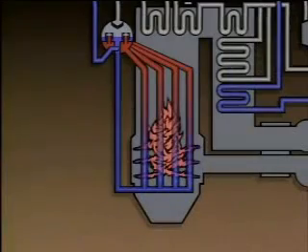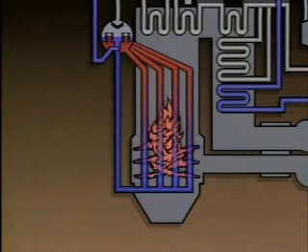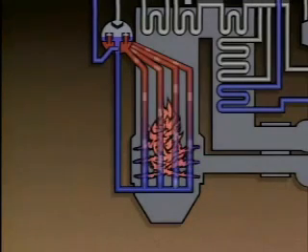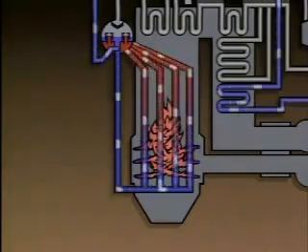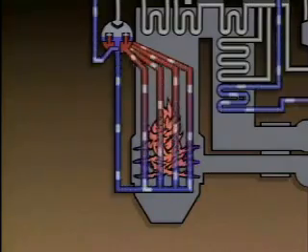The flow of water through some boilers occurs by means of natural circulation. The key to understanding natural circulation is the fact that cold water is heavier or denser than hot water or steam. In a boiler, the mixture of water and steam in the water walls is hotter than the water flowing from the drum through the downcomers. This is because the water walls are heated by the burning fuel in the boiler furnace. As the mixture of water and steam rises, cooler water from the downcomers flows into the lower headers and then into the water walls.